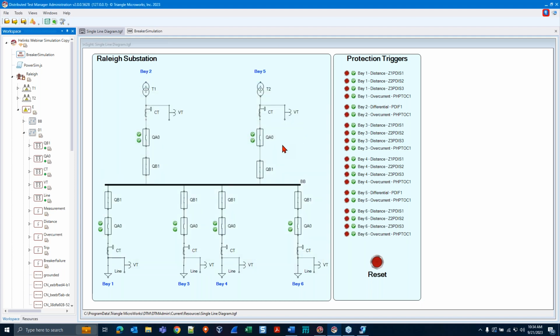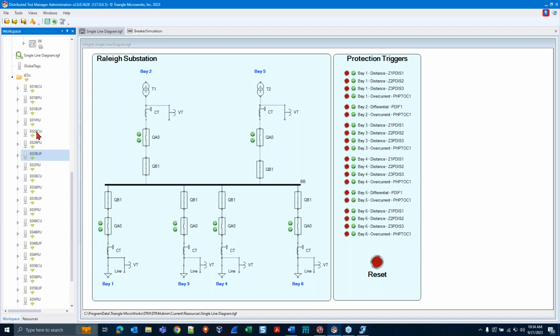To use an analogy, I think of an SCD as kind of like a blueprint for a car, where the frame of the car captured in the blueprint would tell us the different pieces of conducting equipment, where they are within my system, and what they're connected to. You might think of the logical nodes as the different components of the car that perform functions, like the brakes, engine, transmission, and so on, and those will exist down on the different IEDs that we have down here at the bottom.